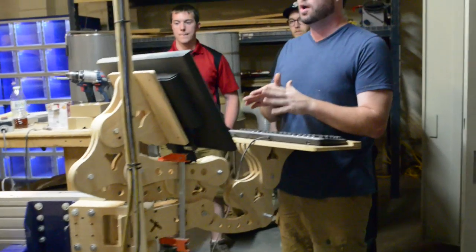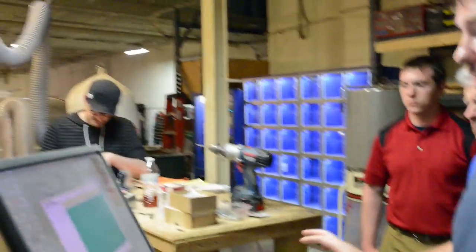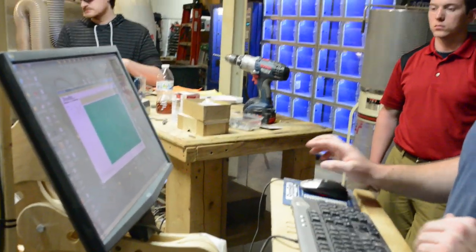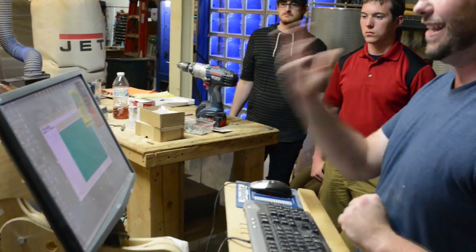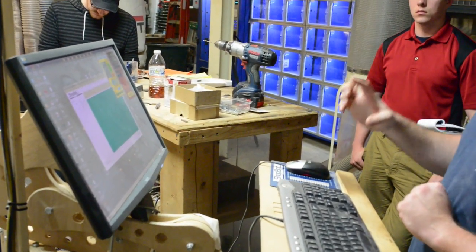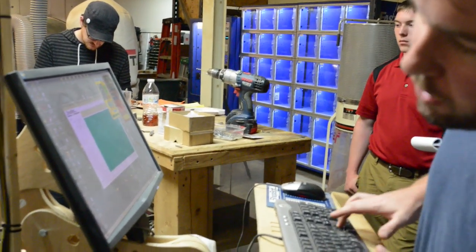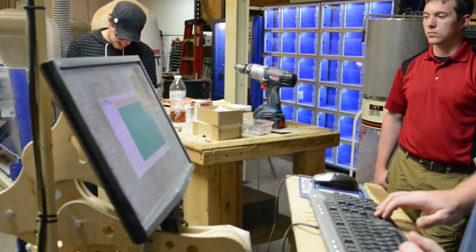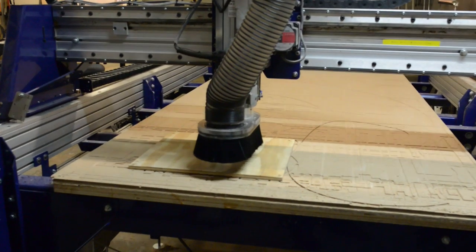Now it's time to zero the coordinates for the machine. So the first thing I want to do is do the Z. So you have to come in here, escape, get out of that manual control, get in the habit of doing that. And I'm going to use the keyboard shortcut for the manual control, which is K. Brings up that exact same box. And to zero the Z axis, I want to move the cutter head over my material somewhere. That's all I've got to do. In the center, on the edge, doesn't matter. So just move it over to my material. I just want to make sure my cutter head is over top of my material somewhere.